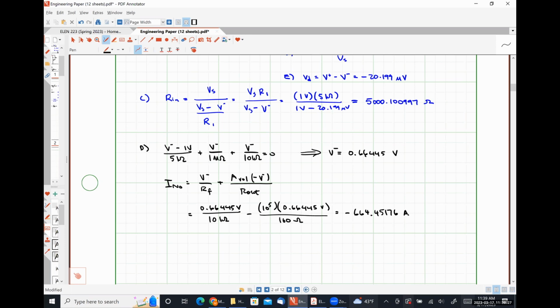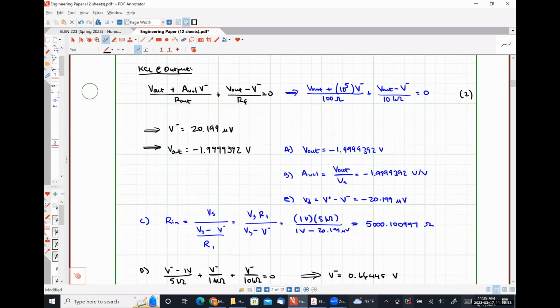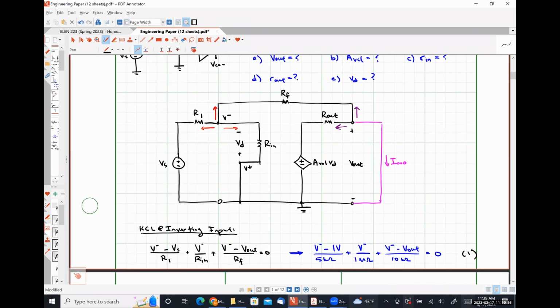Open loop gain, closed loop gain. So the open loop gain is how this voltage generates this voltage, right? So that's the relationship between the output side of this thing and the input side of this, right? So the output voltage present here is the open loop gain times the differential voltage. Our closed loop gain is the voltage measured across our output terminals divided by the input signal that we're applying outside of the closed loop, right? So did that clarify things? Okay.